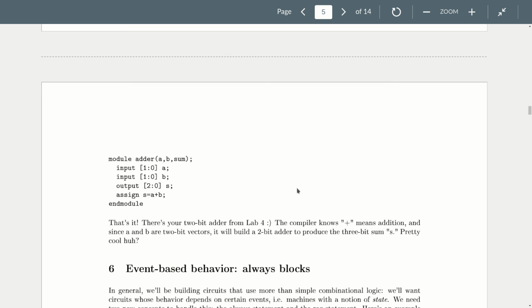It knows how to do addition. If you're implementing this on a piece of hardware that has an actual adder unit, it'll use that. But if you don't, if you just run this through a straight Verilog compiler, you'll come up with a circuit that has a bunch of ANDs and ORs and XORs, and maybe does a full adder, half adder implementation. If the Verilog compiler was smart, and you put in 2 bits for A and B, you get out 3 bits for S.